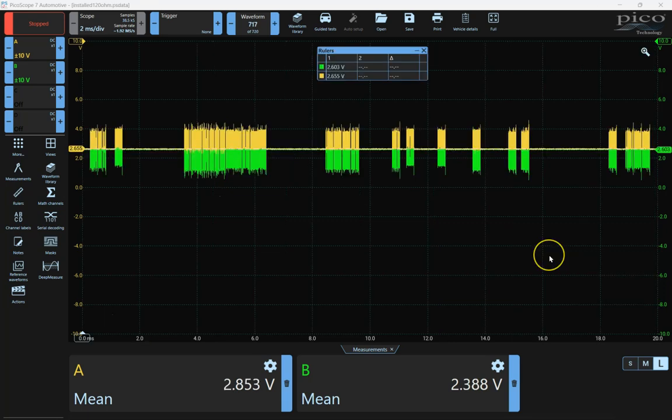time-wise as a bit. Okay, so in this final case, what I did is, with both the active and the so-called passive terminator removed from the machine, I placed a single 120 ohm terminating resistor at the diagnostic connector. So this is somewhere towards the middle of the circuit.